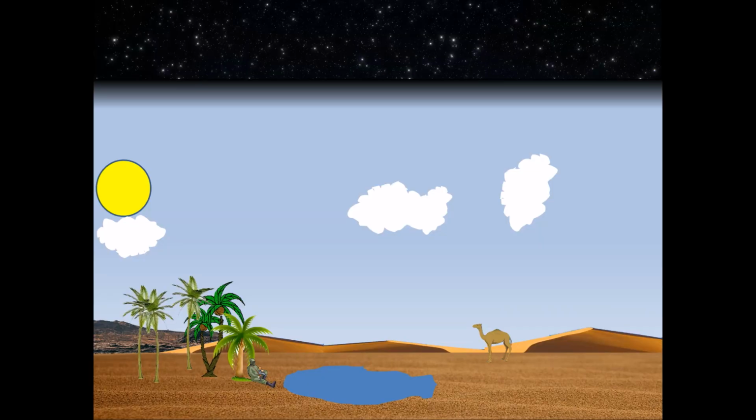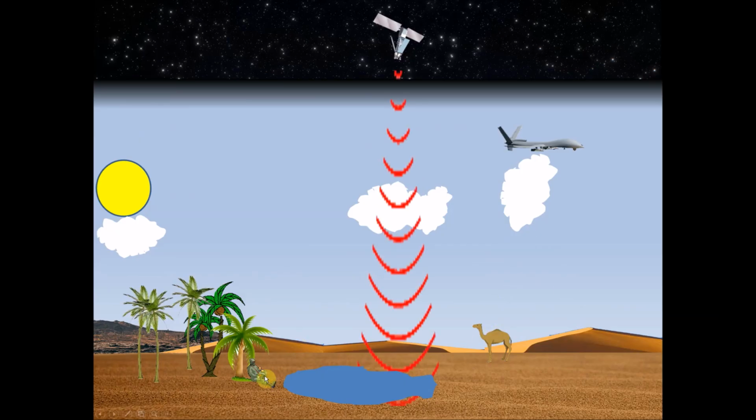So another application of thermal infrared detectors is to look at the heat signature of objects and terrain. So if we are to say look for a person who's either hiding out or lost in a desert, we can look for our signature 310 Kelvin emission from that person, and as such fit these detectors to either a drone or a spacecraft and look for these particular signatures. Of course, there's a slight disadvantage that most mammals radiate at 310 Kelvin, and as such, telling the difference between a human and an animal can be difficult.